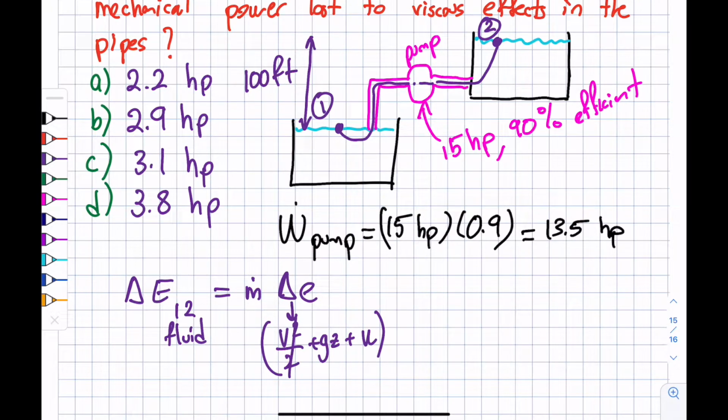How about the internal energy? We'll talk more about this in module 3, but you know already that the internal energy, or more specifically the specific internal energy, depends on the temperature and pressure. The state postulate determines that I need two properties to define my system. So you can see here, just because it goes from here to here, there will be no significant pressure change because it's open to atmosphere. This is open to atmosphere, and I don't anticipate the temperature to go up significantly.